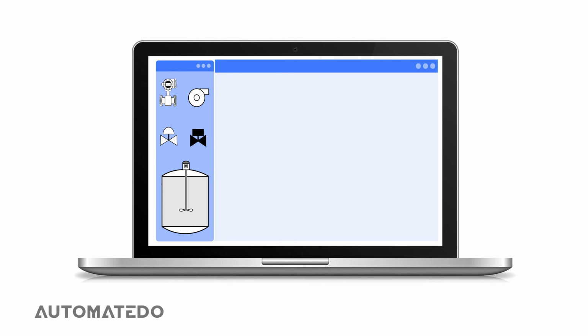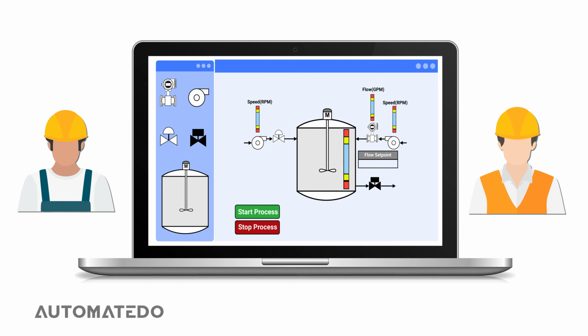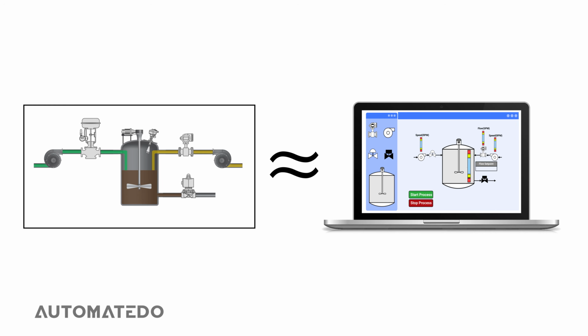First, development. A personal computer is used to program the HMI through a special software. The HMI software allows engineers to design a graphical screen of what operators will see to monitor and operate industrial machinery. If you are interested in HMI programming, you should consider some essential design tips, such as user awareness. Consider the users who will be using it and think about operators' limited knowledge when it comes to operating industrial processes. Visibility. The system's design should sufficiently resemble the actual process to provide users with a positive interface experience.